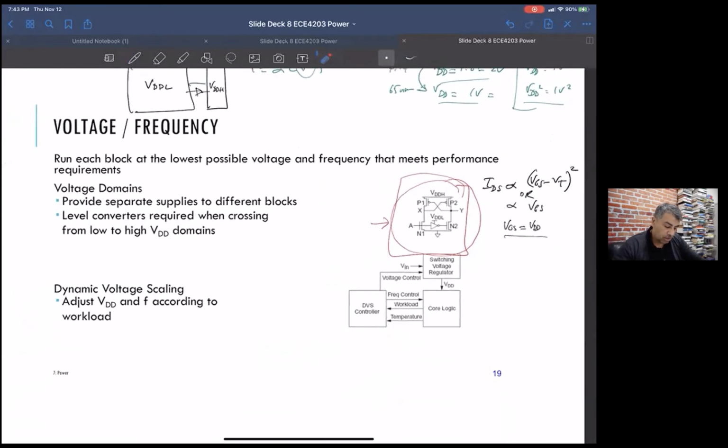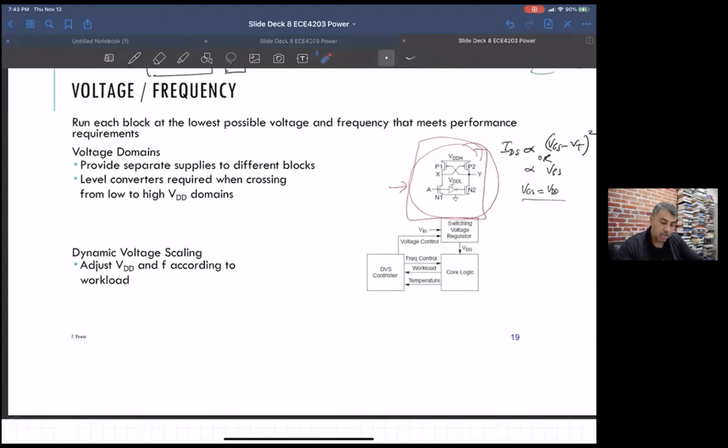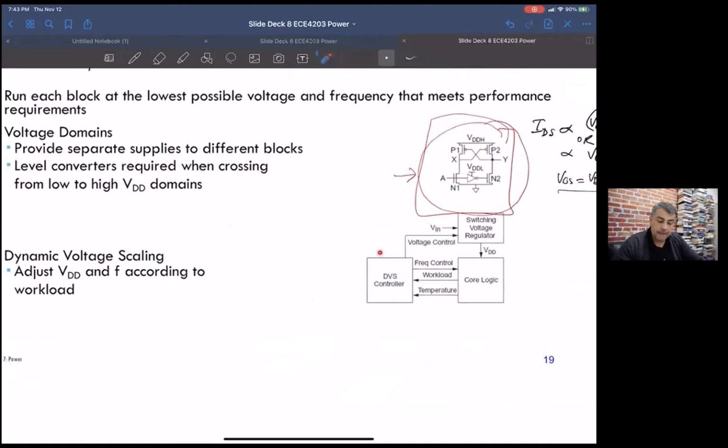Another thing that's really cool, just a great concept, and it works great, although it takes a lot of work to build, is you could look at the actual operating frequency, how fast a particular logic block is going, and when it's going slow and when it's going fast. And you can put it in a feedback loop with a voltage regulator. So when it's going slow, you'll drop the supply voltage to the logic block.